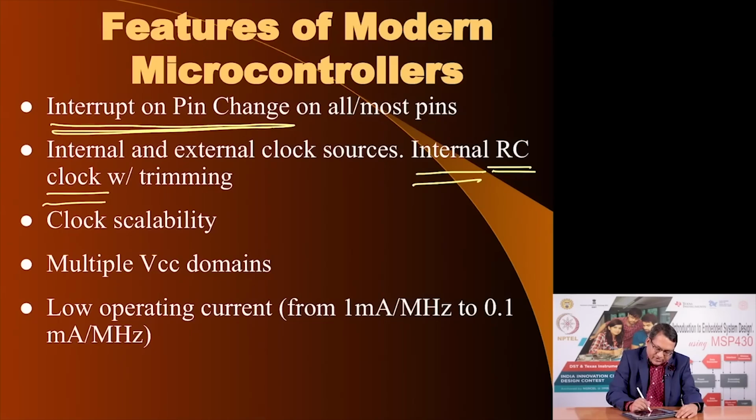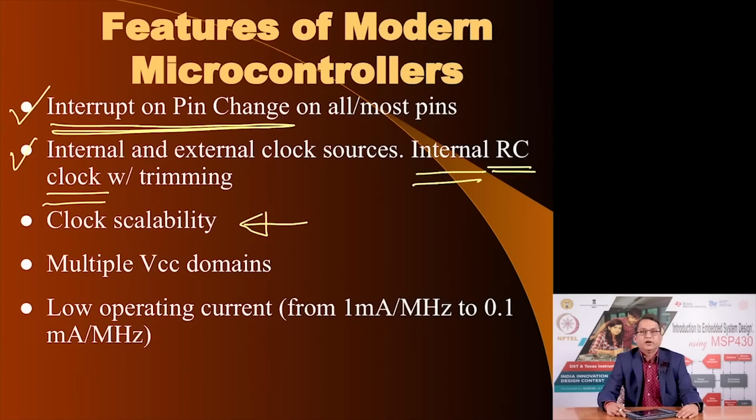Now another interesting feature that these microcontrollers offer is what is called clock scalability, and in fact MSP 430 offers this feature. What is the meaning of clock scalability? Meaning that you can change the system clock, the internal clock or external clock signal that we were just talking about. You could change the frequency of that clock at runtime. Normally you would fix the frequency and you may not want to change it.